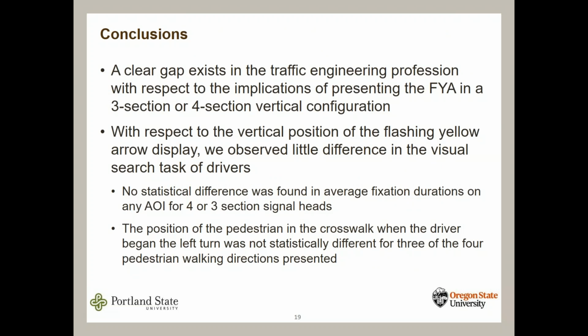So in terms of conclusions, at the time when we conducted the experiment, there was a gap in research. Folks were looking for guidance on whether a 3-section signal head would be adequate in these left-turning bay, exclusive left-turning bay scenarios where we were conducting PPLT phasing. So as we think about the performance measures that we collect, we couldn't differentiate in any meaningful way either the response of the driver to starting their left turn in relation to the position of the pedestrian or the active visual search task. There was no difference between either of those measures in the 3 or the 4-section case.